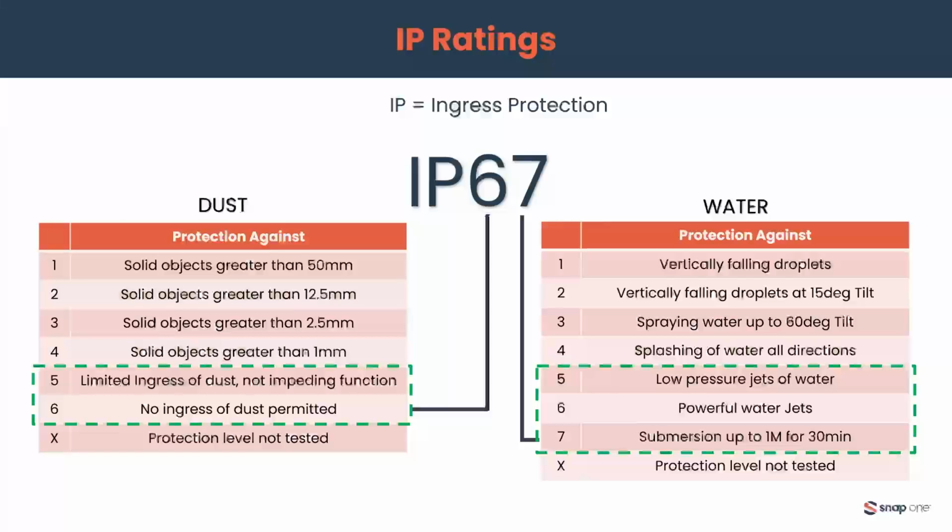There was a question on ceiling speakers having adjustable tweeters. Depending on the model, the Signature 3 series has a pivoting or rotating tweeter. The Core series all weathers do not. There was a question on wiring connections. So obviously different speakers have different wiring methodologies. Our landscape speakers have a pigtail, so you would just wire the system up in parallel using included silicone-filled wire nuts. All-weather surface mount speakers have a gold-plated push terminal on the back, and so you could again take a pair of speakers, twist them together, and put them into the push terminals.